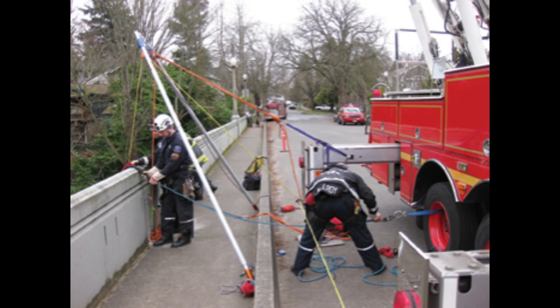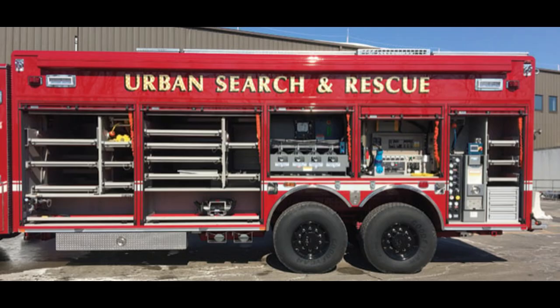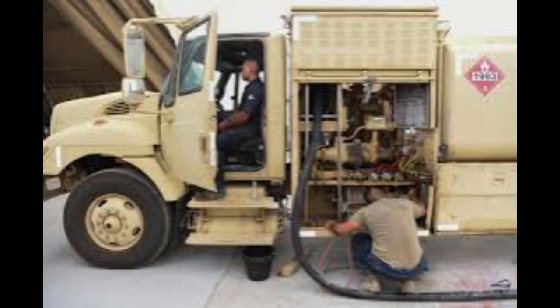Maintenance. Perform any required maintenance functions, including fluid checks, tire pressure, brake inspections, and operational checks of specialized systems. Identify any issues and schedule repairs as needed to maintain vehicle reliability. Cleaning. Clean both the exterior and interior of all vehicles. Remove mud, debris, or contaminants that may have accumulated during the operation. Clean vehicles reduce wear, prevent corrosion, and present a professional appearance to the team.